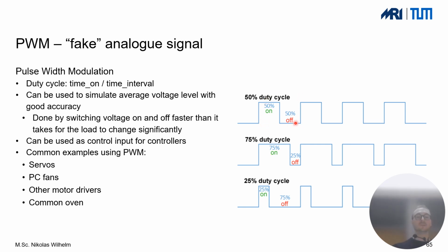So for example, here you have an activity of 50%, here 75% activity, or here 25%, and you can then alter that as you need. What the actual motor or output device will then be doing, and this is how it's often solved, is for example your servo motor will be active for this amount of time with maximum torque, and then be shut down for the rest of the time. But because the frequency is so high, that will appear to the output of the actual motor to be an operation at 50% of the output torque, in a way.